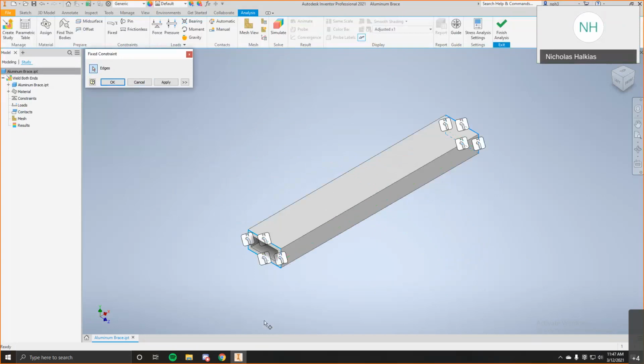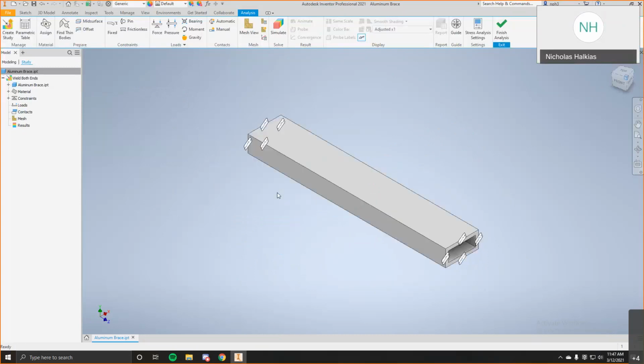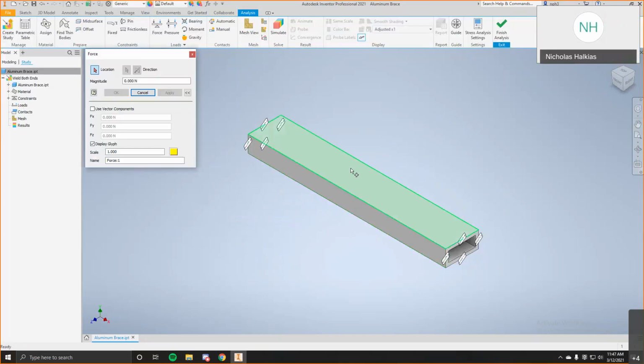And there we go. We just have all of our selected sides, and we're just going to press apply. Now that's all done. Next on the list is our loads. So I'm just going to put a force right in the middle of this face. Now you notice that it is in newtons.